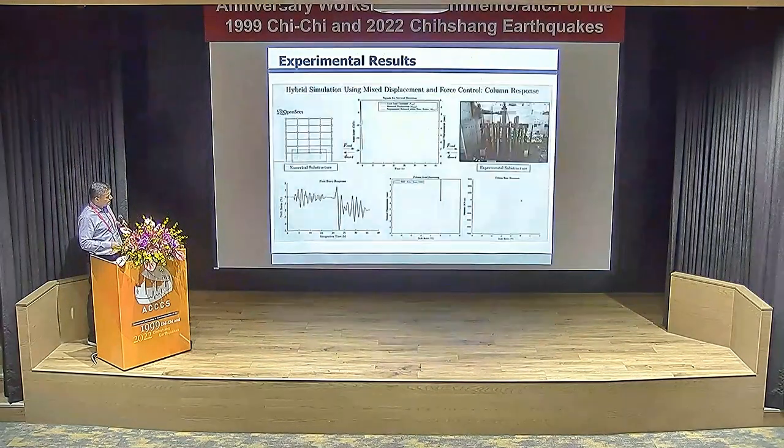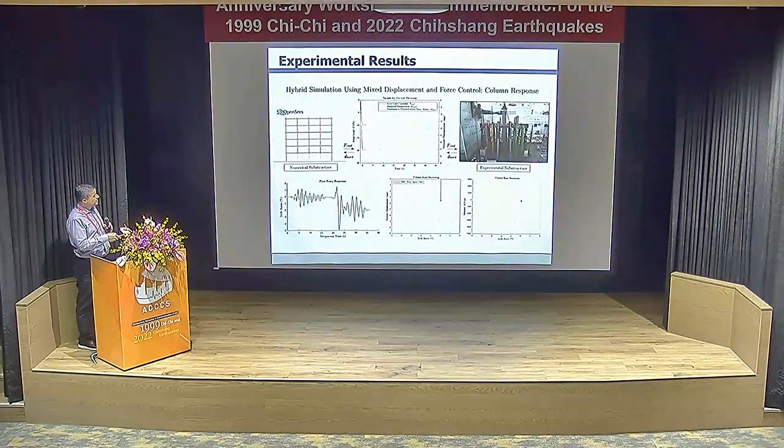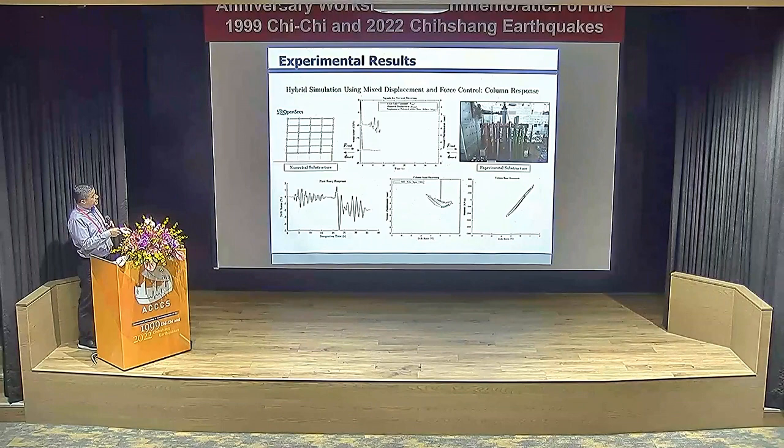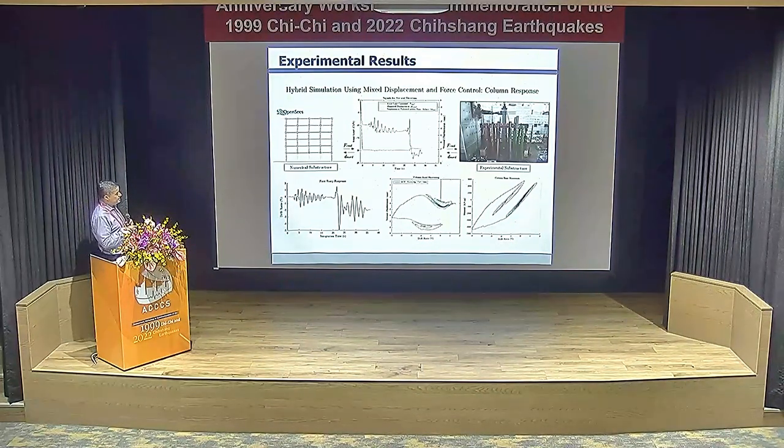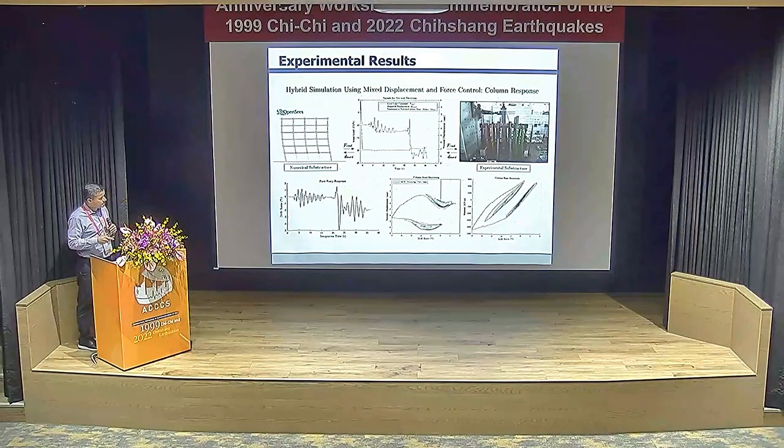This is a video to show the mixed displacement and force control. So this is a video that's going to start playing, but you see the axial load command to the actuators that's tracking, the measured displacement, and how it tracks with the numerical simulation. It's easier to see the displacement here compared to the drift, how that's varying, and the shortening that's happening in the columns. This initial jump here is just from the gravity load, and then as we go to the MC motion, you see a significant increase with the pulse in the motion.